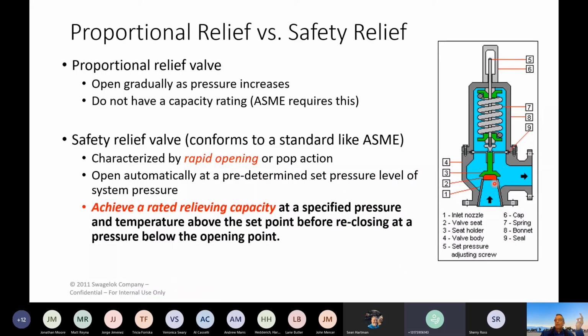And how that's done is that on the right here, you have a higher pressure and you're exceeding your set point. Typically, this over here would be atmosphere. As this opens, you have more surface area on this poppet. Surface area times pressure equals force. So as this cracks open, you get more force, more surface area exposed, and it will force this safety valve open, all but 100% open.